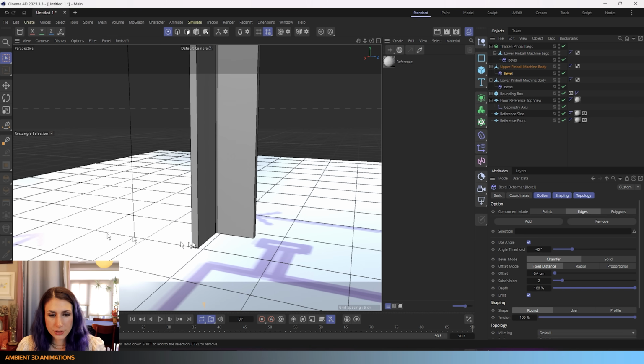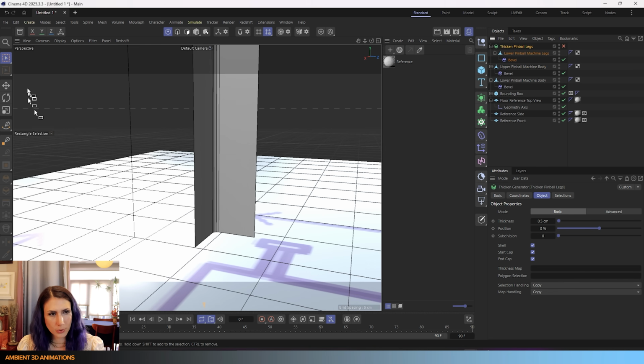Now usually for sheet metal like this, there would be some kind of part coming out at the bottom that's welded, and then maybe they put a weld nut on the inside of this so that the leveler feet can twist into some threads. So we're missing that part actually on our feet, so I'm just going to turn off the thicken here for a moment.